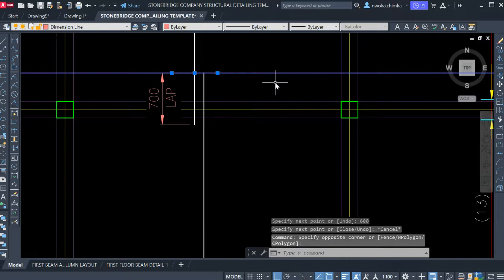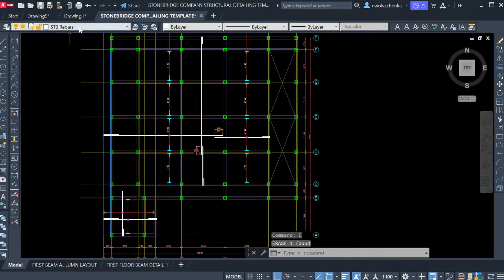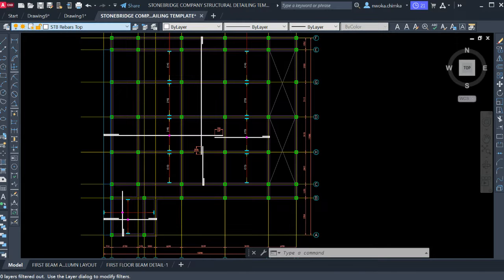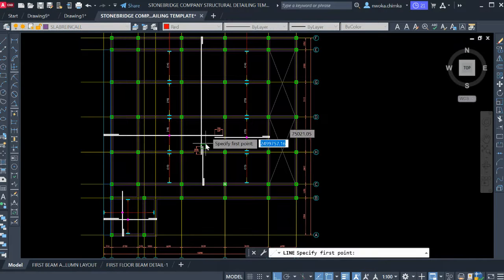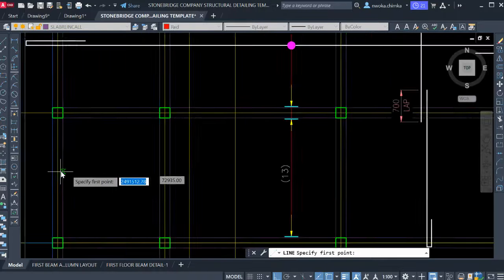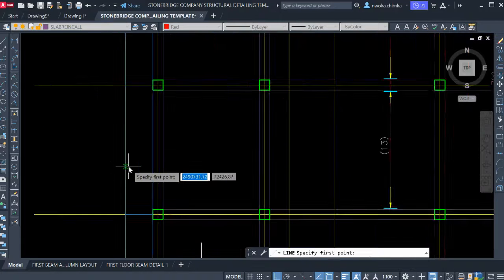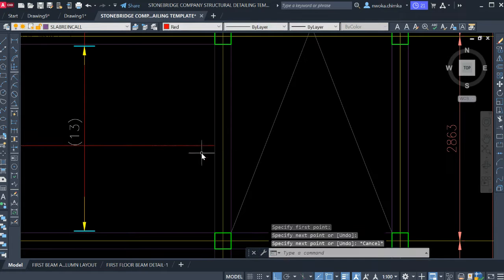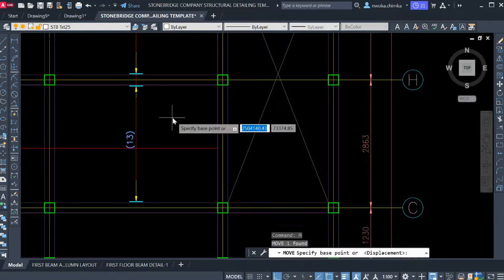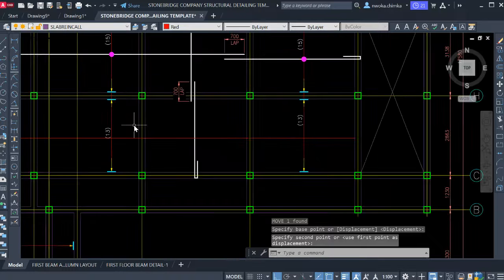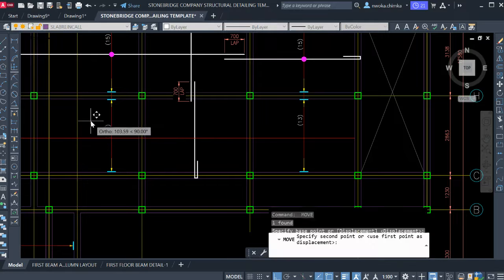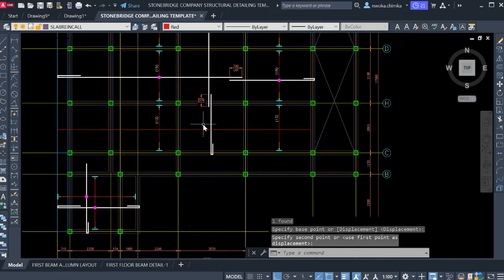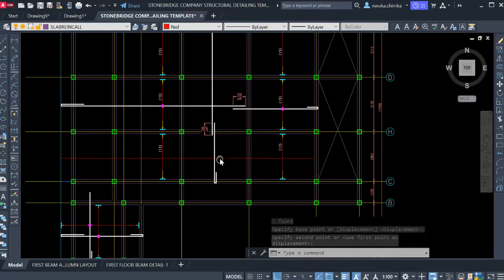So you can now remove this, and then bring out our call out line, which is S ring bar. So click on this, change this color to red immediately so we don't make mistake, and then click on this point right now. So I want to detail this right now. So we just click on this point again. This goes like this, and so detail from this point to this point. Okay, you can see that. So you can just move this upward a bit right now so it will not conflict, and then this also should not conflict.